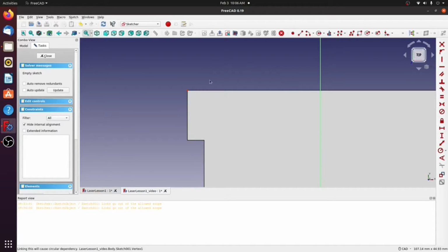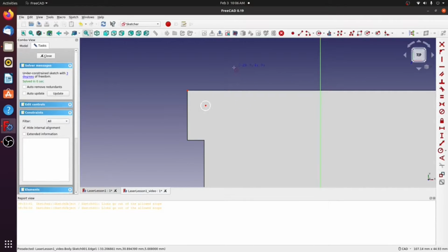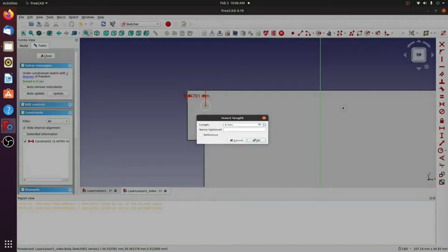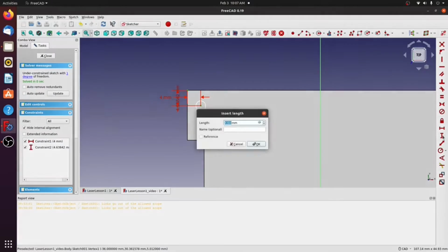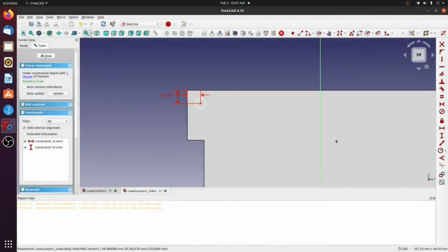You can probably guess already that we're going to use this as an anchor point for creating our standoff peg. So just like before, I'm able to go in, grab my little circle tool, just like that. Then we're going to highlight that external reference, and we can use it just as if it was in the same sketch. So let's make this 4 millimeters over just to illustrate things. 4 millimeters vertical constraint. There we go.